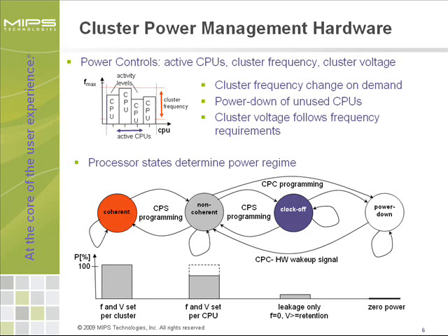Now that we have studied basic requirements, let's focus on the core functions of the cluster power manager. As initially claimed, two basic variables can be used to manage power in a multiprocessor cluster. First, available execution parallelism. This reflects directly in powering down unused CPUs. Alternatively, unused CPU's clock can be turned off.